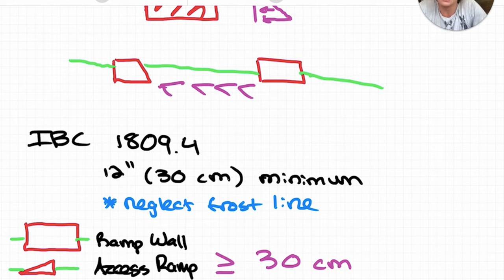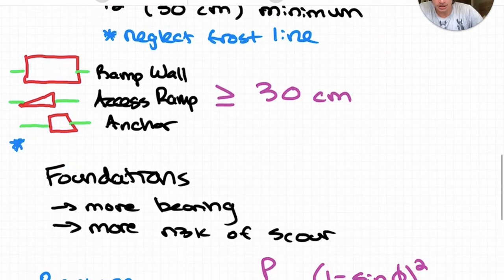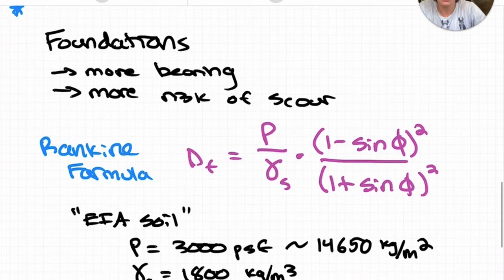The minimum is to realize full bearing capacity of the soil and minimize any differential settlement that will lead to cracking and loss of capacity. Now regarding foundations, bearing capacity and therefore any differential settlement is much more of a concern, especially in three-tier abutments. There's also more exposure to any scour from water runoff and wind.